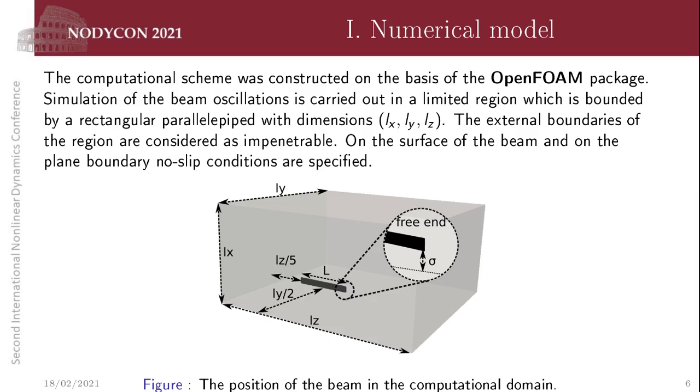We solve the problem numerically. The realization of the computational scheme was done on the basis of the OpenFOAM package. Simulation of the beam oscillations was carried out in a limited region, which is bounded by a rectangular parallelepiped. The external boundaries of the region were considered as impenetrable. On the surface of the beam and on the plane boundary, no-slip conditions were specified.